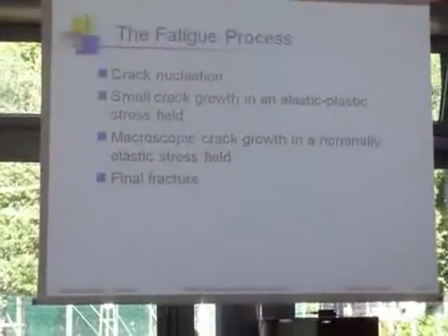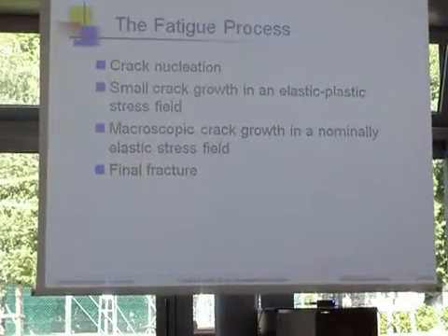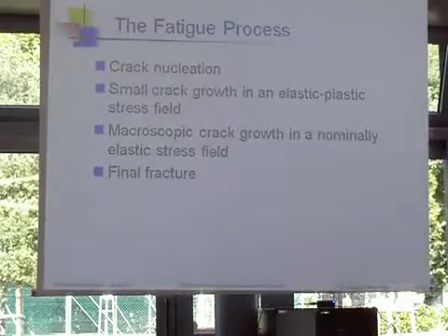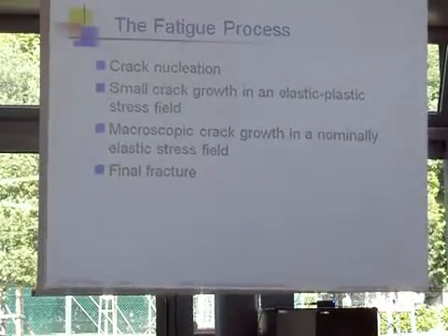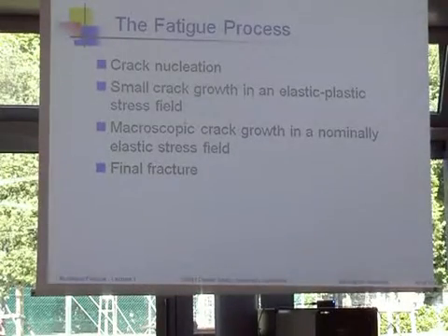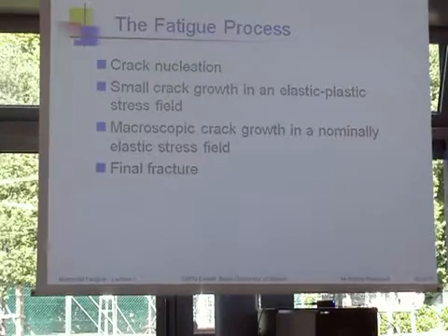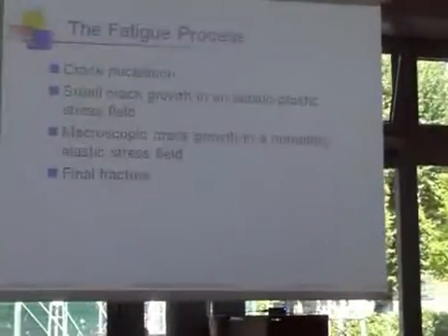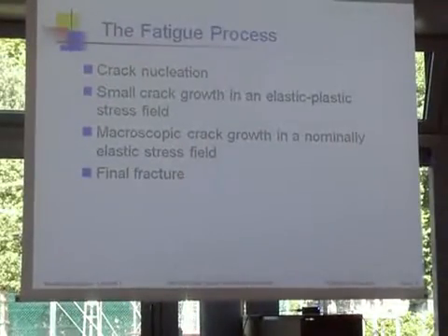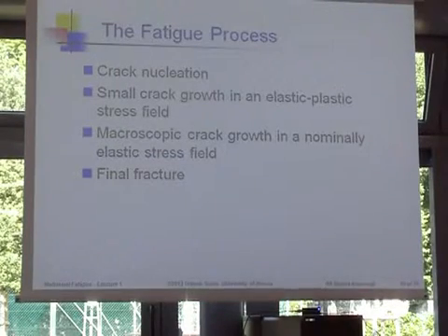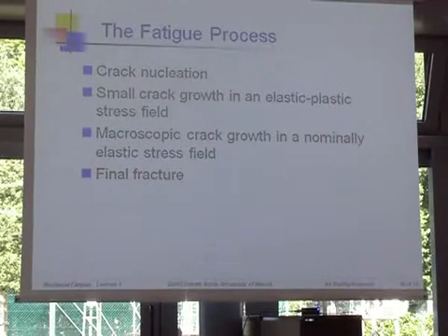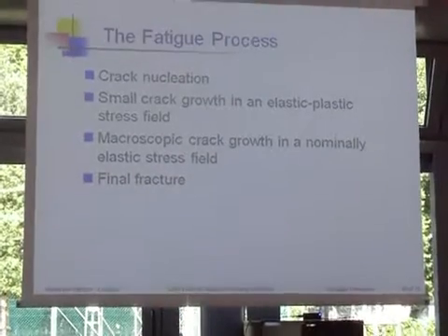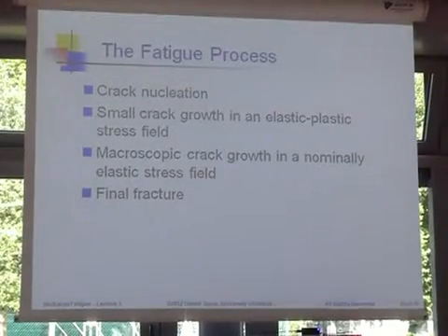And so this is what I think of as the fatigue process. Cracks have to start if they're not already there. Then to get a failure, you need small crack growth in an elastic plastic stress field. If the stress fields are all elastic, even around the cracks, you don't have fatigue problems. There's not enough driving force. And then, when the crack gets bigger, you have macroscopic crack growth in a nominally elastic stress field, and then finally it breaks. So, depending on where most of the life is spent, people try to model one or the other aspects of the fatigue process.